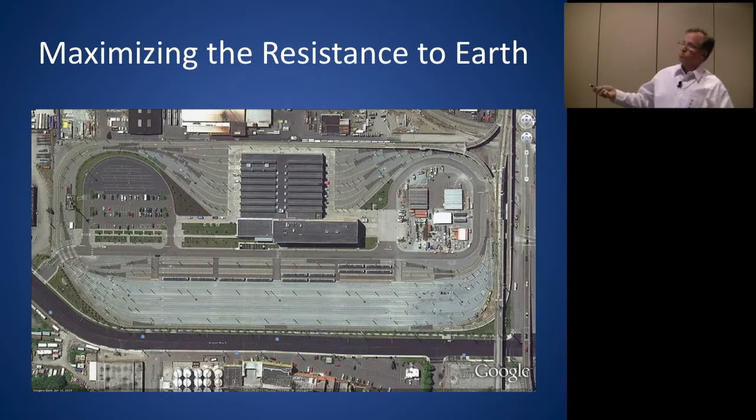This is a typical yard. Okay, this is the shop right here. This is where they do work on the trains. They have a lot of tracks coming here. Right off this, what they call the apron, we put a set of insulated joints right in here. And this is all grounded track in there. The amount of power they use inside a shop is very low, so there's not a stray current problem. We do a lot of bonding around it to contain any stray currents.